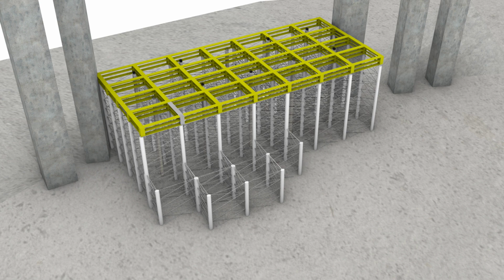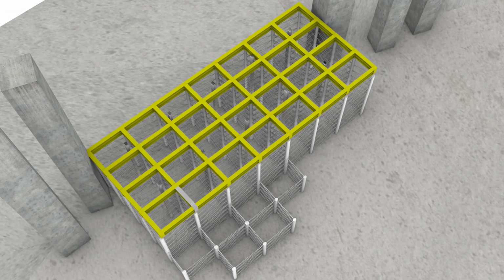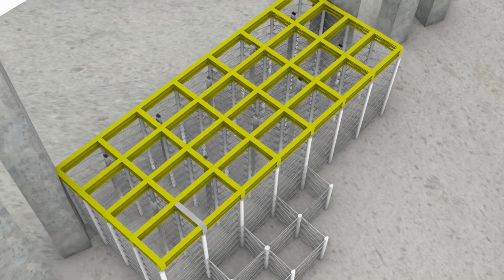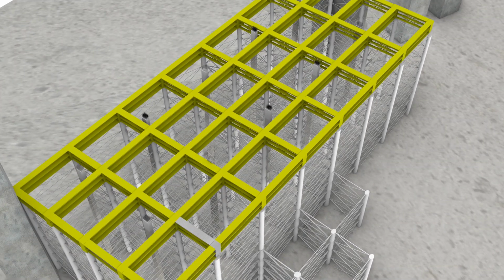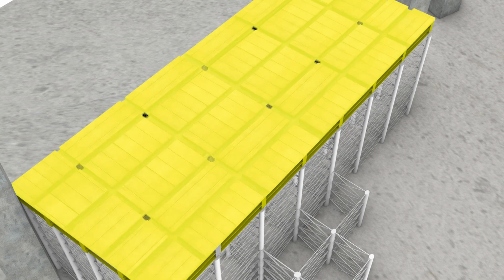To handle the wide slab area and concentrated loads, steel I-beams or truss members are installed horizontally across the top of the vertical pipes. These elements help evenly distribute the load and serve as an accurate reference plane for installing the formwork and reinforcements. The plywood formwork placed above these beams includes pre-cut grooves, which are essential for shaping the integral slab and beam structure.